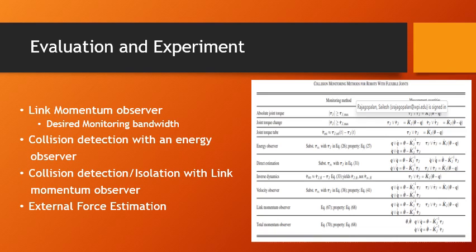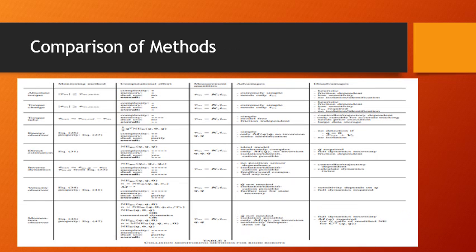Joint monitoring methods can be dynamic or algebraic estimation of the associated external joint torque via an energy observer, along with monitoring the tau external via inverse dynamics and estimating the tau external via a joint velocity observer, as discussed. In the table are the three known industrial schemes, namely monitoring the absolute torque, the torque change, and the torque tube.